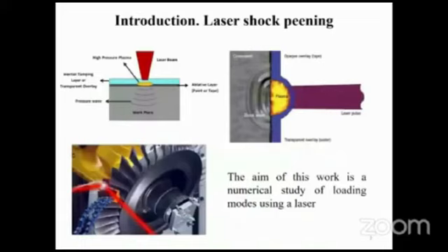Laser shock peening is one of the promising methods of surface treatment of materials for the purpose of hardening. This method makes it possible to practically get rid of the effect of heating of the near-surface layers, which is very important for materials with a unique structure, due to the absence of recrystallization processes that level out the previous thermomechanical treatment.